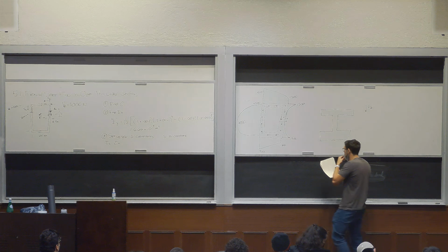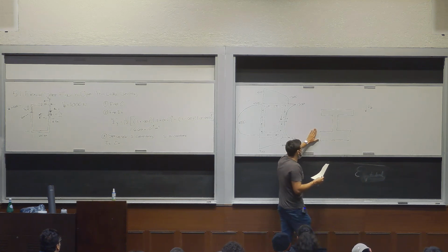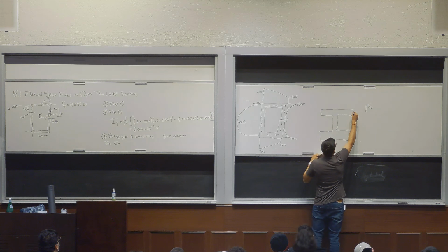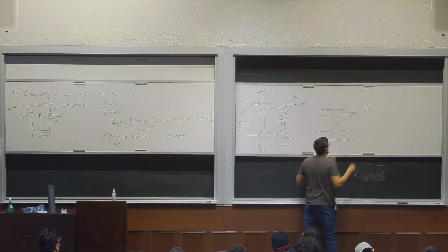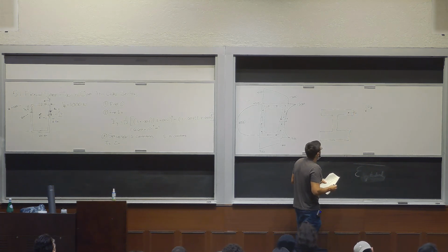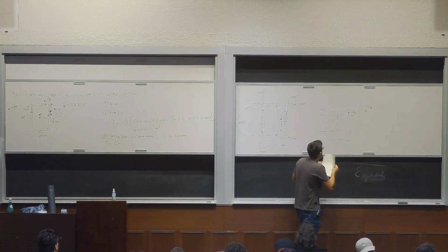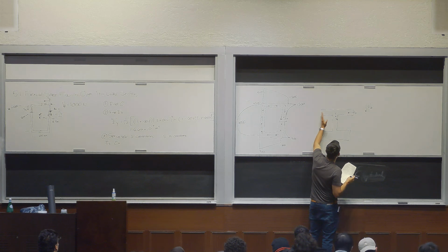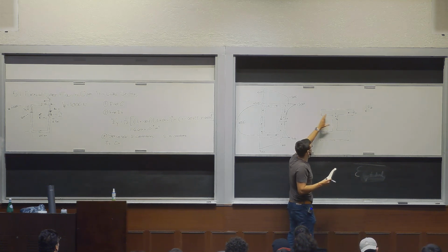But going back to the topic I was just describing, for this specific cross section, you can't just add it progressively, right? It's not a little loop. So you have many open-ended sections. We could define this as S1, okay? But then, I guess you could make this S2. But then you're ignoring all the first moment of inertia of this portion, right?